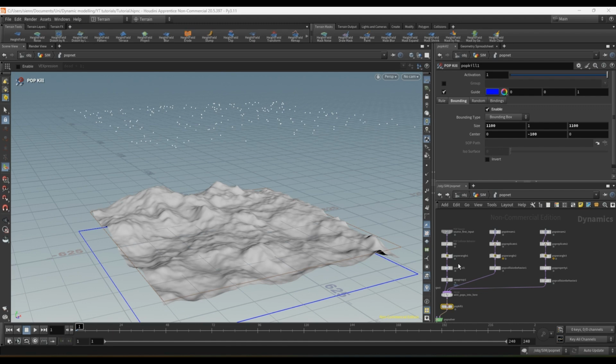Last thing I want to mention is the frames. So this bar at the bottom plays the simulations for you, but it's limited to a certain amount of frames. If you find that the video is a bit short and you want to show something that will happen later on, then you can change the start and end frames. If you put in too many frames for the video, then it will take a really long time for your computer to load. I would recommend not going over 300 frames.